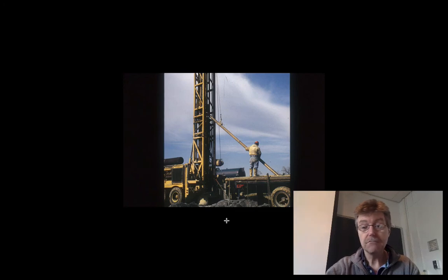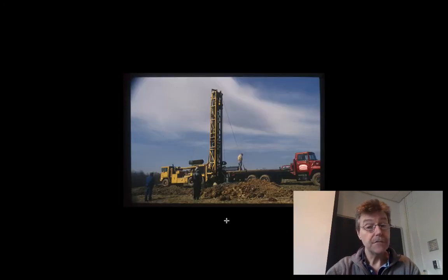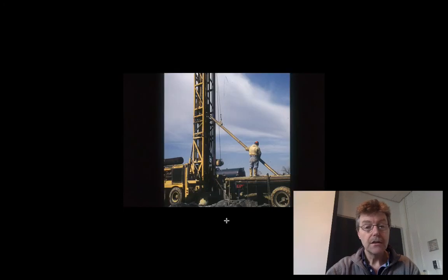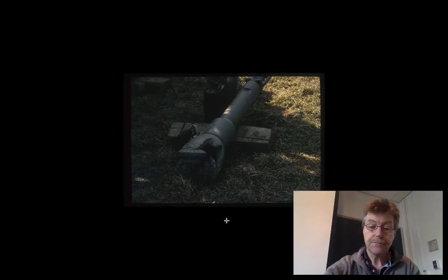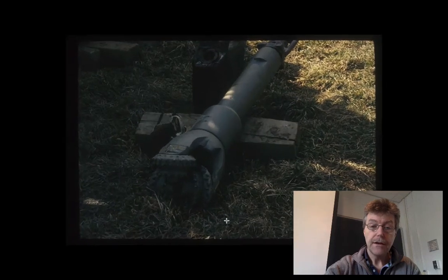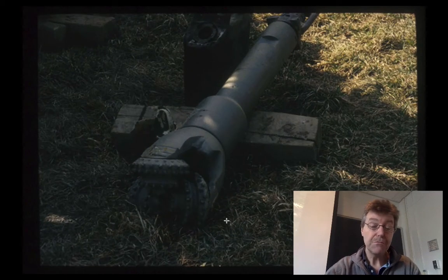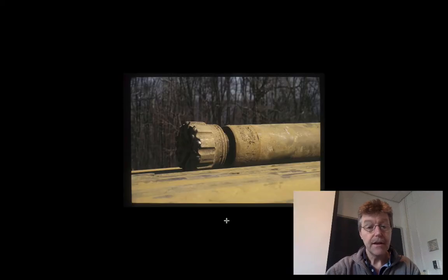Didn't see these. This is in Pennsylvania, a rotary rig, in this case drilling with air, drilling with a very big rotary bit, probably 14 inches in diameter, to get through the surface to the rock top and then put casing in, and then a hammer drill.